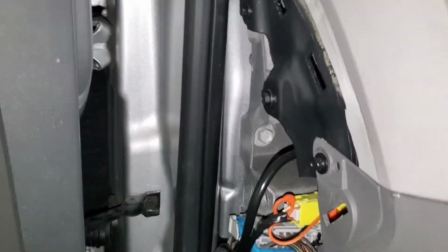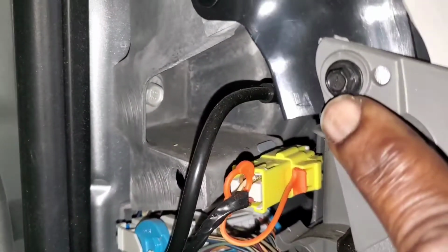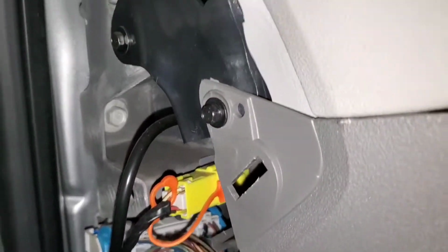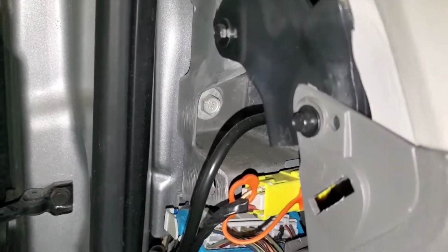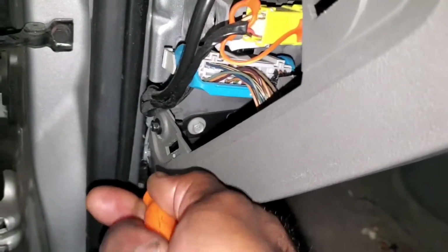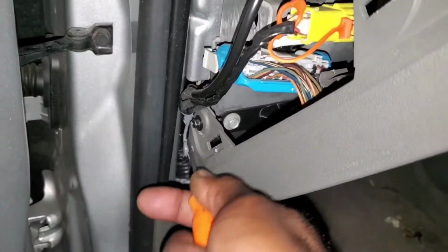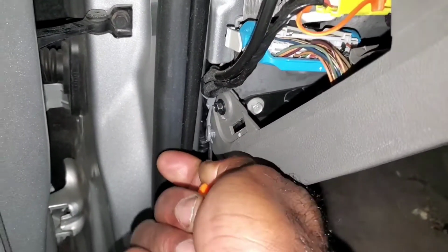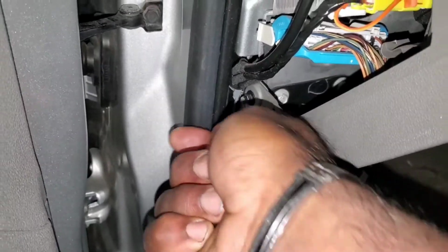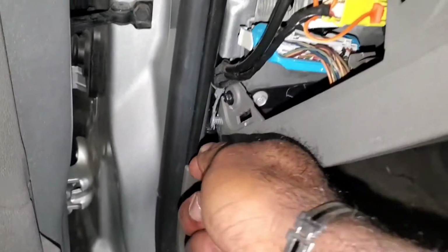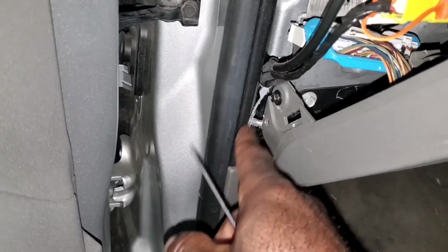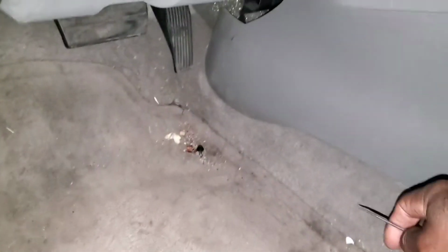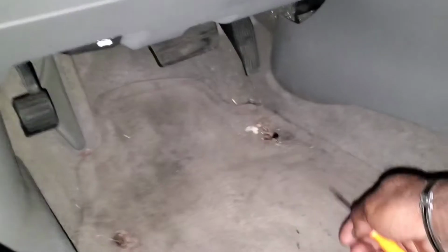Now I want you to keep an eye on a couple of things here. These are your 7mm that hold this from the top. There's several as we go along. Actually, before I forget, let's remove this. This is a harness clip, like a Christmas tree style. It just zips in. So let's get that out of the way before we start struggling with it later. That's just out of that bottom hole. We'll put that in later. Let's pry this out. Don't know if I can reach it from underneath.